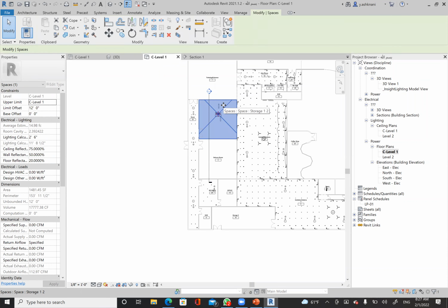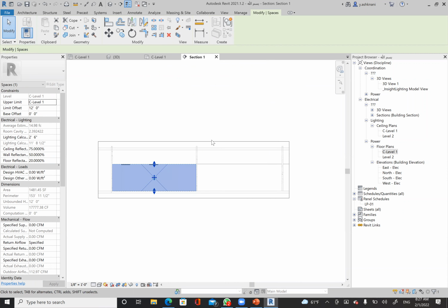And this is 14.98 foot candle. Oh, okay. Now it's changed. Because the space needs to reach there. This foot candela, we are seeing in the space. Earlier the space was still below, till 8 feet only. Your lighting is at 12 feet. So your lighting was out of the space, and so for sure it will not show up in the foot candela.